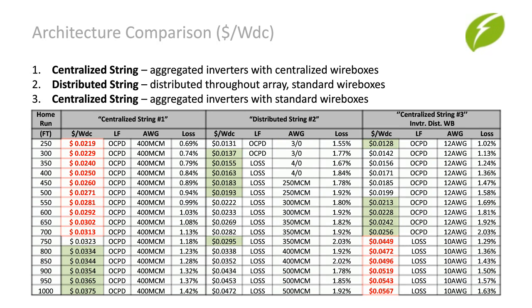At $1,200 each for the combiners, they would cost $19,200. But if we use inverters with a standard wire box, eliminating that $19,000 external combiner cost, we would be spending about $5,000 more for the inverters. So that's a savings of about $14,000.